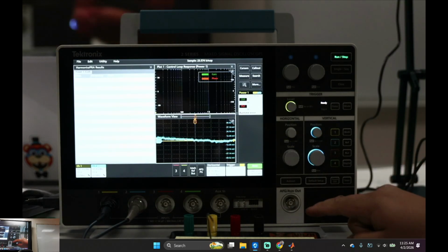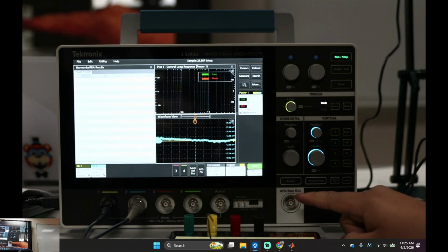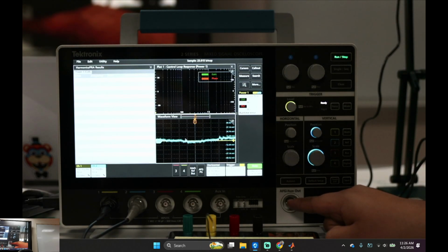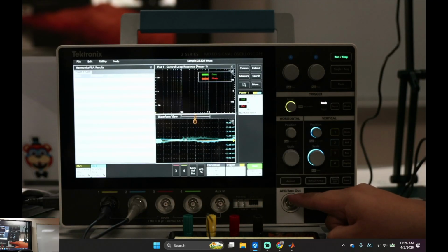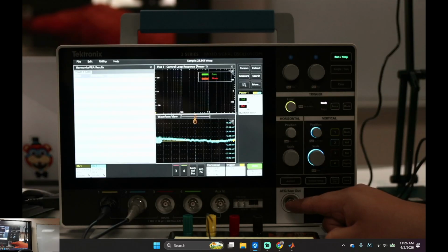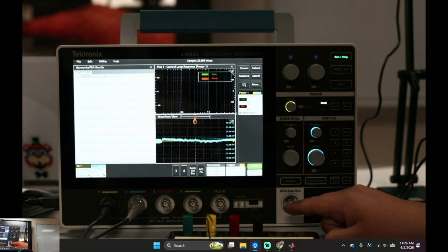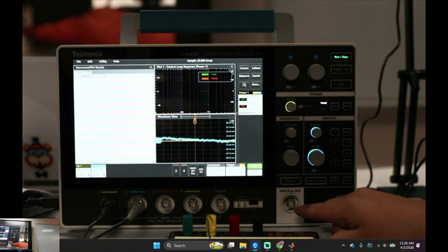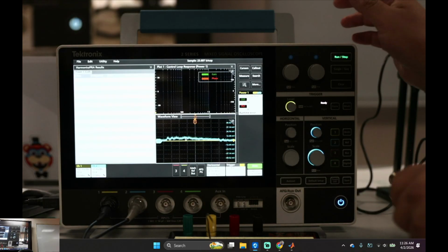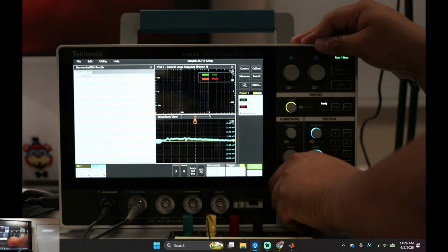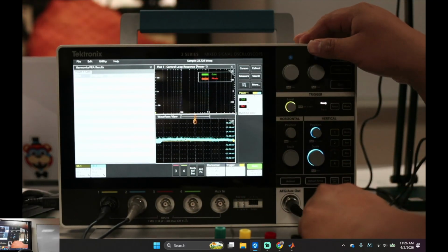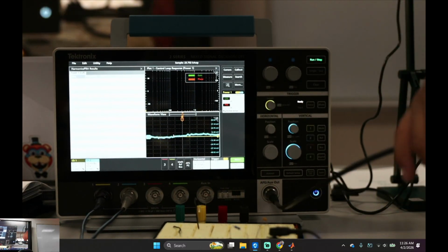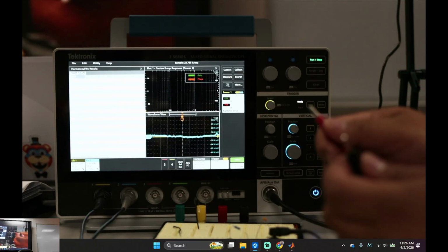So all the oscilloscopes in here have something called an arbitrary function generator, AFG, and it's disabled because I don't think Dr. Greg purchased them originally when we got them. So I bought this for this one right here, so this one works now. I only have two of them. This acts like a function generator. Now I drop the circuit, just push it right there. So now I have my input signal.